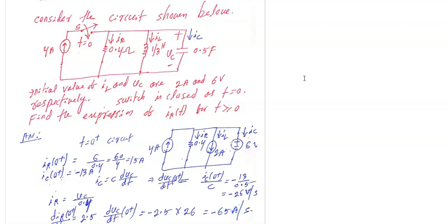What are the laid down procedures? First, write the circuit after the switching. What will the circuit be, series or parallel? Two options will be there. Then you write the characteristic equation, then solve the characteristic equation for the natural response. There you will have your arbitrary constants that need to be found later on.